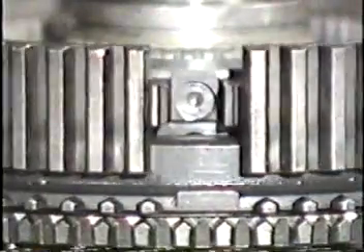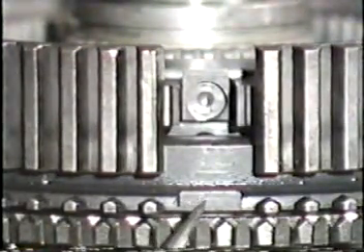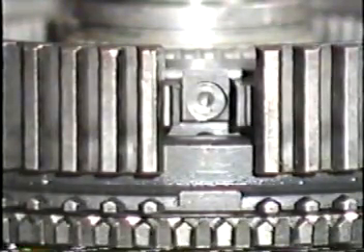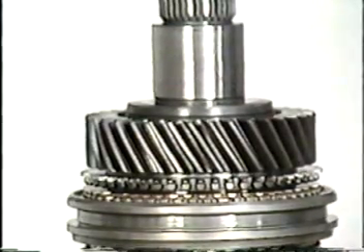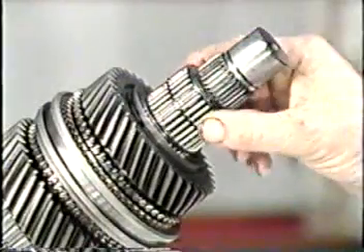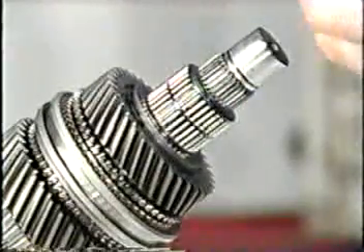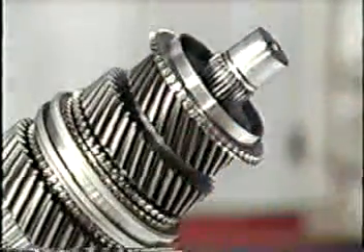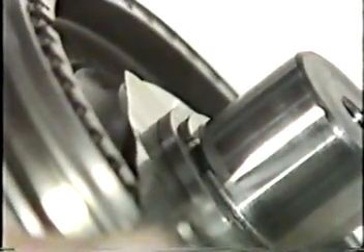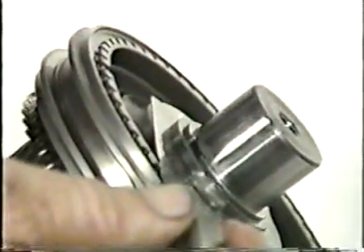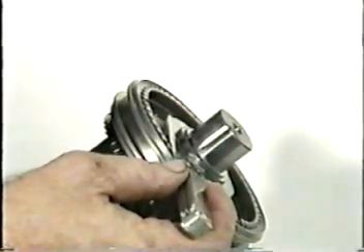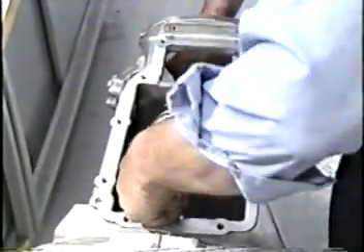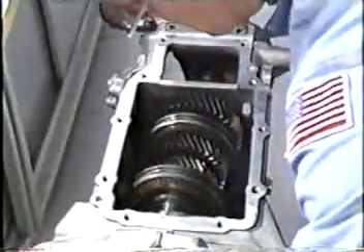To reassemble the synchronizer, align the new synchronizer rings with the insert keys on the hub. Make sure the reference mark faces the rear of the transmission. Reassemble the long side, making sure to lubricate all rotating or sliding parts with Mercon as you do. Then, install the short side components. Check the clutch hub end play using a feeler gauge. If the measurement is not within specification, obtain the proper thickness retaining ring and install it. Now, the sub-assemblies can be reinstalled and the transmission reassembled.